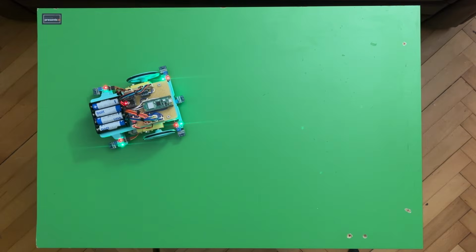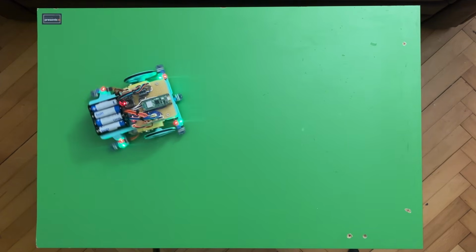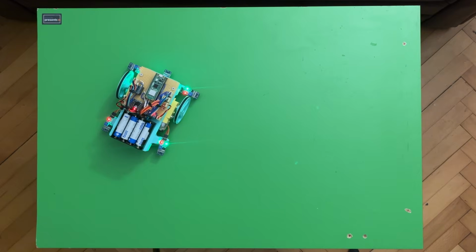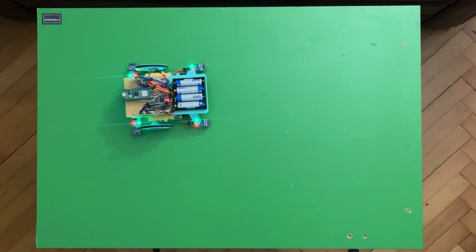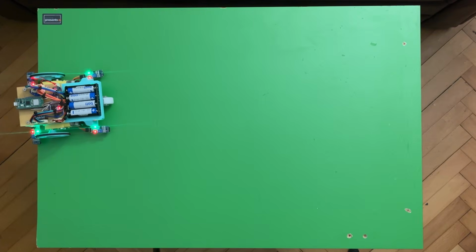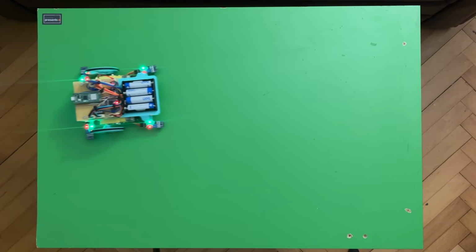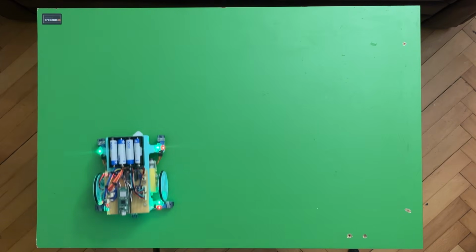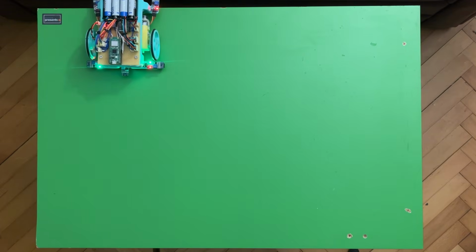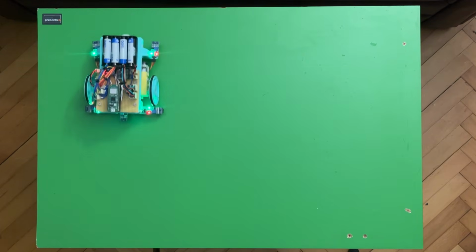The robot is now on the table and we can finally drive it around. So as you can see, we can do some simple turns, we can go forward, we can go backwards, and you can see all of the sensors light up. But if we try and run it to the edge, you will see the robot stops. There's a couple of ways we can implement this. One way is through the graphical user interface, but that can have some lag and the robot can fall over. Or if we do it directly in firmware, that's a much better and more stable option.